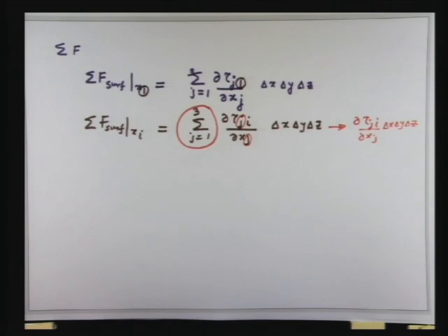The angular momentum conservation we will see is inbuilt by relating tau ji with tau ij. So there is no separate angular momentum conservation equation that we use in fluid mechanics, but we can use tau ij equal to tau ji, which I will prove in just a moment, in the linear momentum equation. So the momentum equation that we use in fluid mechanics is a linear momentum conservation, but has the consideration of angular momentum conservation inbuilt within it. Let us look into how it is inbuilt.